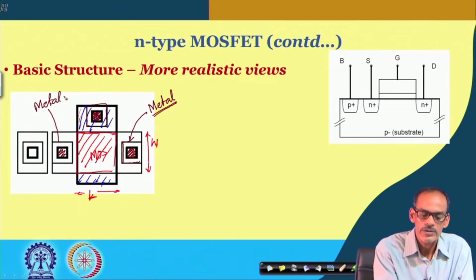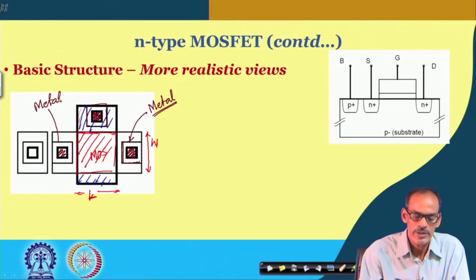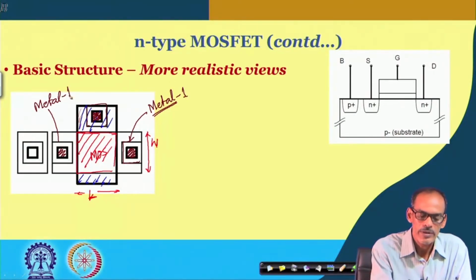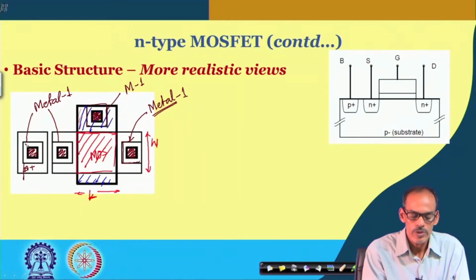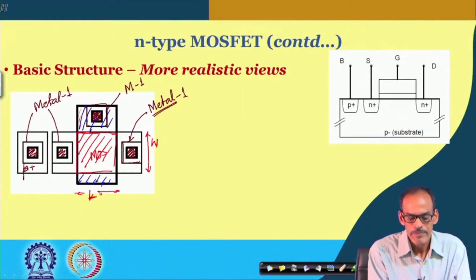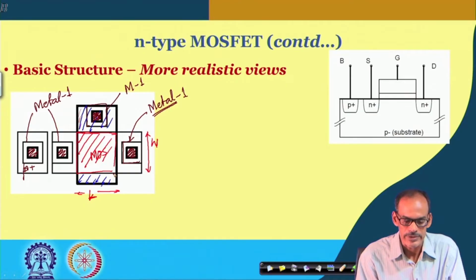And in fact, in an integrated circuit there are different layers of metals. So, typically this metal layer is referred to as the metal 1 layer. So, in fact, this is also the metal 1 layer. So, it is called met 1, and we have the P plus region here for the body connection. So, here also we have the contact and then metal 1. So, if you see the top view here, it is rather like this.